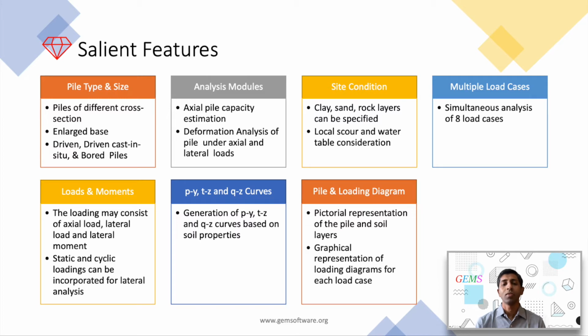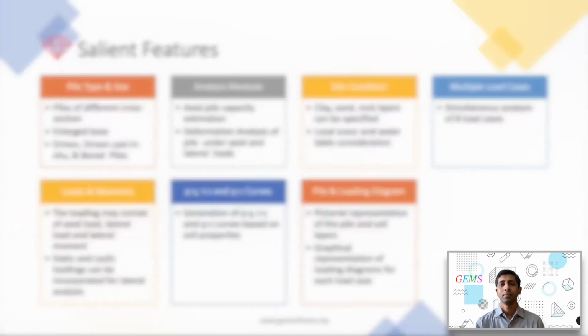Loading may consist of axial loads, lateral loads, and moment. Static and cyclic loading of the pile can also be incorporated for lateral analysis. The application supports generation of PY, TZ, and QZ curves based on soil properties. There is a pictorial representation of pile and soil layers, and a graphical representation of the loading diagram for each load case for easy visualization of the loading.